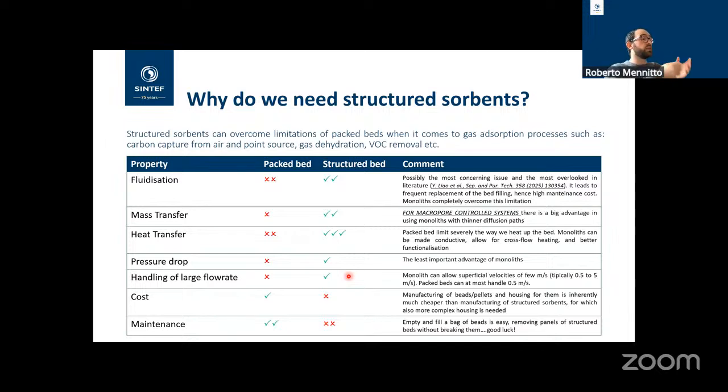So even resistive heating, if you think about it, a packed bed of activated carbons might easily burn because you form closed circuits in the packed bed, while structuring a bed allows you to transfer heat from the sides or from the inlet and outlet. So I do think that the main benefit that we will see will be in temperature swing while working with heat transfer. And again, it's a personal statement that is literally supported by literature, but I hope that we will find more literature on that.